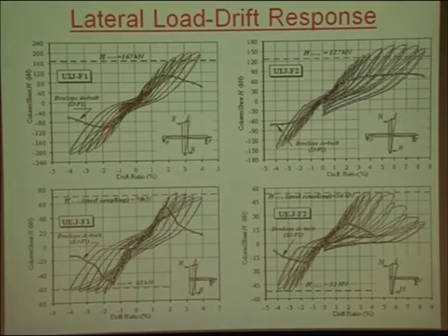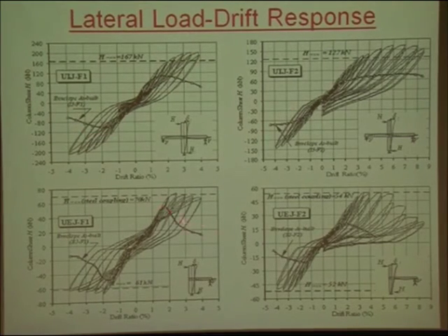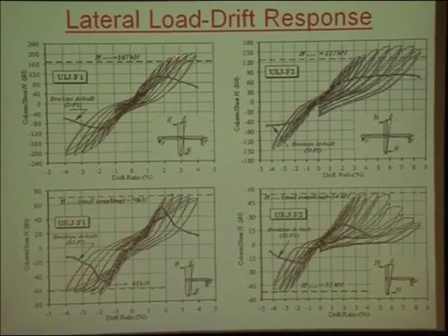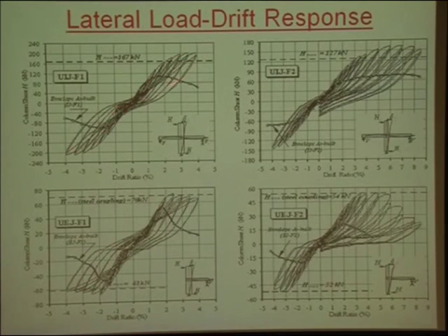So you can see these are the earthquake-resistant joints. These are the current ones. You can see how the load capacity decreases very quickly. While if I provide reinforcement, you see this performance is extremely good because it's stable. There is no loss in load capacity with increasing drift of the building. This is the column, the load that I can apply, the earthquake load. It's a stable behavior. While for the current structure, this is the envelope line. I'm not showing all the slides over here, which show that it will collapse immediately.